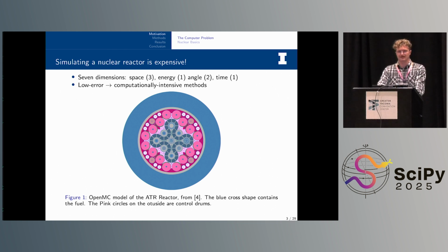So you have lots and lots of surfaces and regions that you have to discretize in your solution method. We have 2 solution methods that we use. We have these deterministic solution methods like finite element method, finite difference. And then we have the Monte Carlo method where we use random sampling to simulate a neutron bouncing around a reactor. Fun fact about Monte Carlo, it was actually invented by John von Neumann and Stanislaw Ulam in the 40s to simulate this exact process. Now it refers to a more broad term of methods that are used in many different scientific domains.